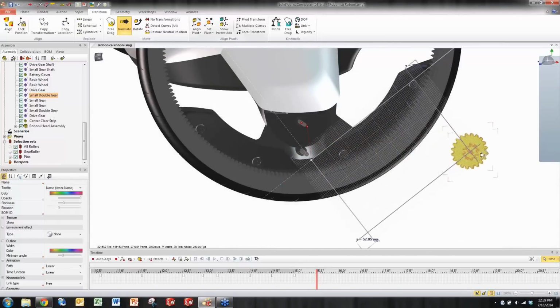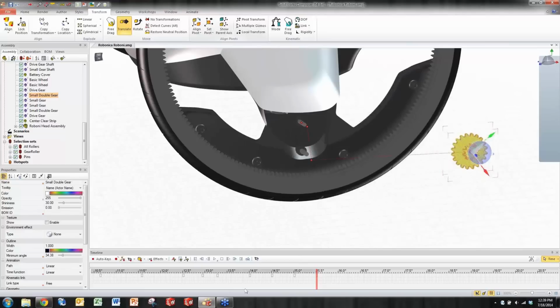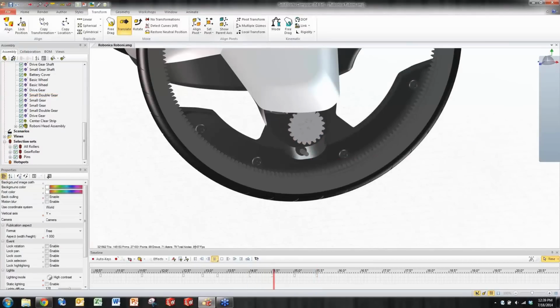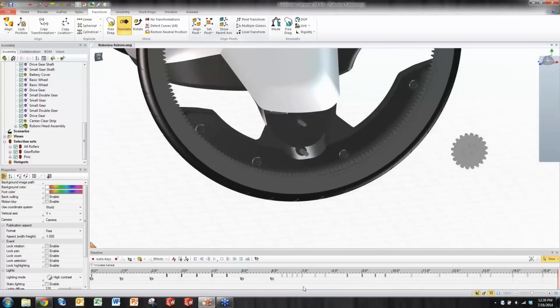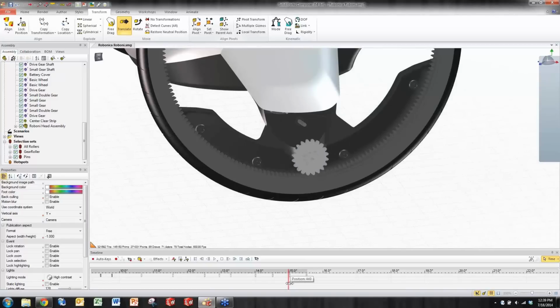So if we watch what's happening here, I'll go ahead and hit play. Comes out, drops down, goes to the side. I already know this last portion of my animation. Oops, I double-clicked, which shows me my entire animation. I can just zoom back into where I was. So I like to see just second markers. So we'll go to here. I'll notice that last, because it's such a big distance, still only happening within a second, I'm going to go ahead and move this one key out to another half second beyond. So now when this thing animates, it comes out, moves, and slowly explodes out to the side.